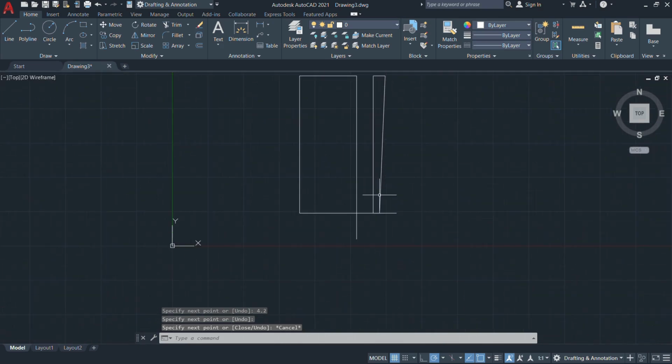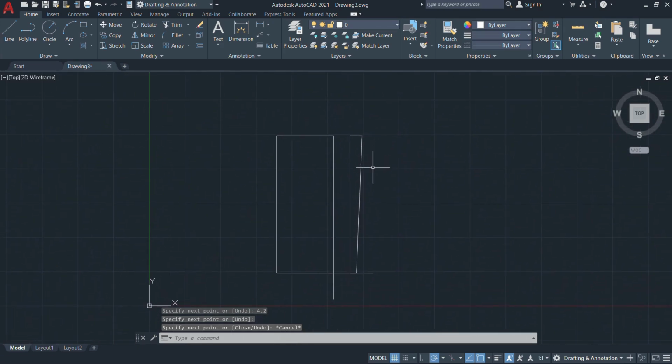Same as that, we are going to draw profiles in the right portion area. Again, choose a line profile and start from its top endpoint. The first horizontal line distance is 4.2 mm. Again, select a line profile from this endpoint, mention 2.25 mm, and connect the two opposite endpoints. The whole profile is now drawn.